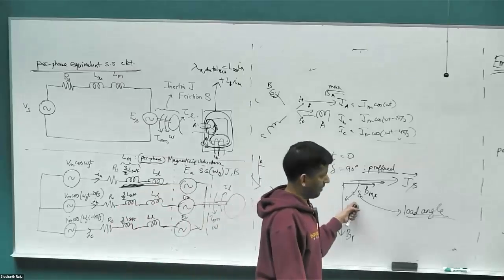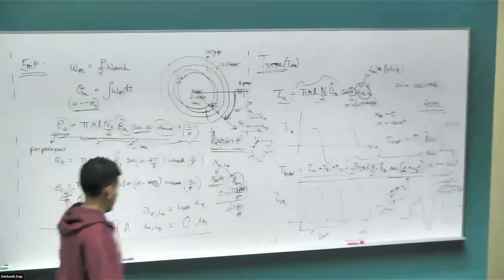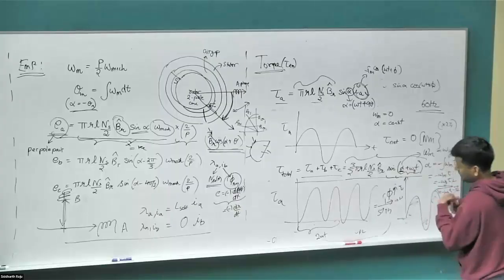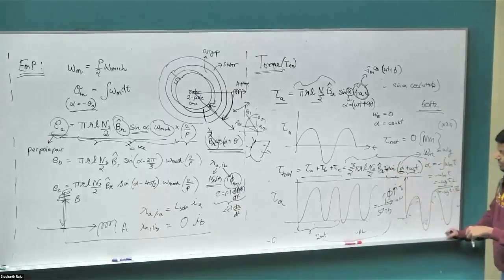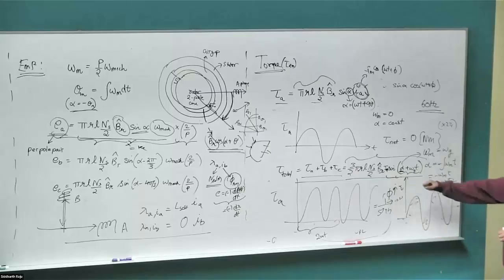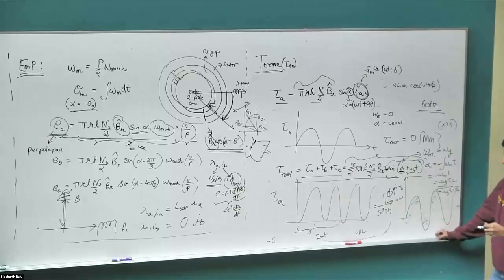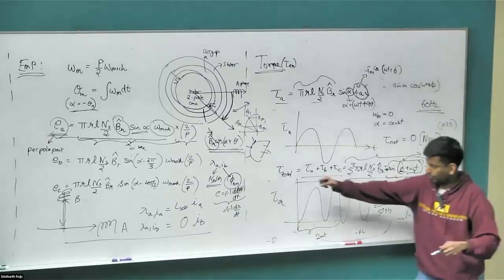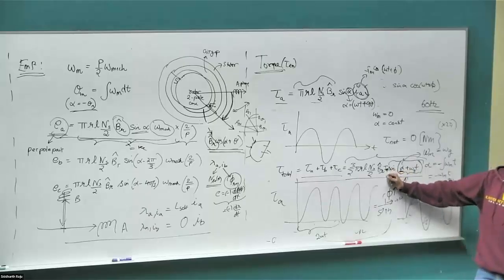So if I were to make the sine of the angle 90 degrees, if you go back to this torque expression, the Im term there, if I make this 90 degrees, this term has become its maximum that it can be. So for a given amount of torque, if this is maximum, then I can reduce the current that needs to go in the coil to produce the torque.